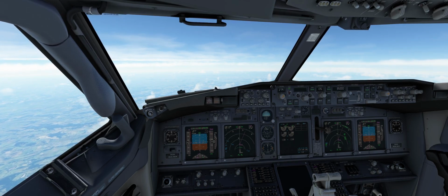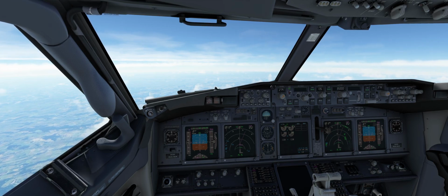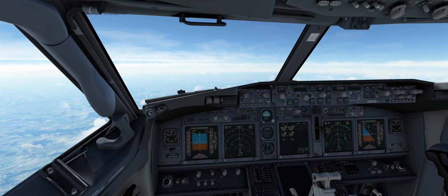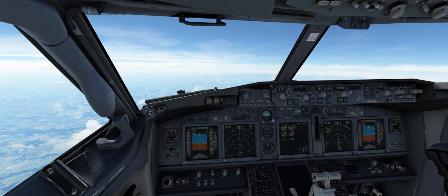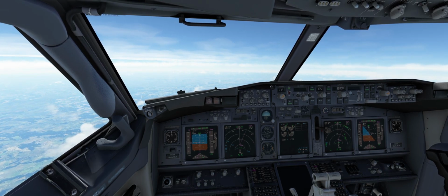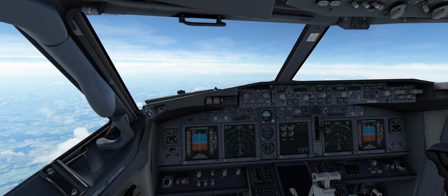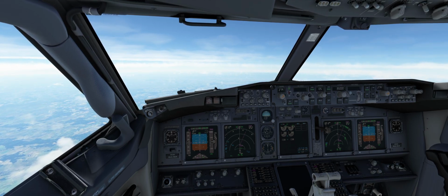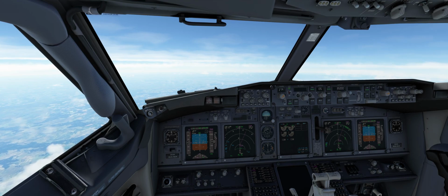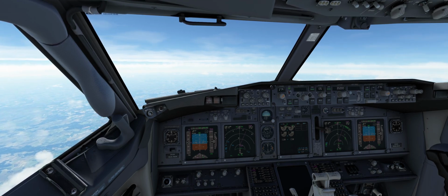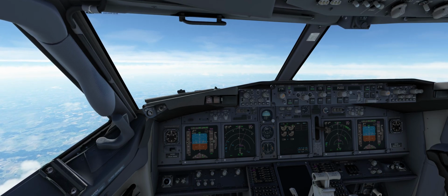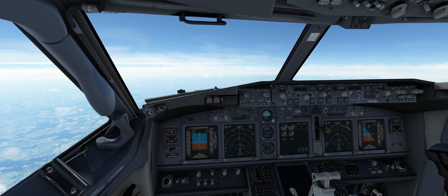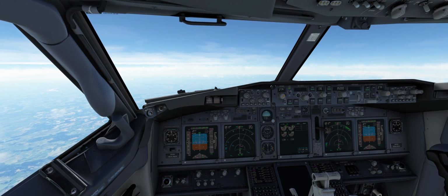If you lose your engine, always remember it is related to Mayday code. There was plenty of discussion that if you lose one engine, it is only pan code. No, please be aware of the fact that when you lose your engine, it's always Mayday. So you have to declare the Mayday code, and it's simple. If you check the QRH, Quick Reference Handbook, you can see that there is a written plan at the nearest suitable airport. That means that you are really in big danger.